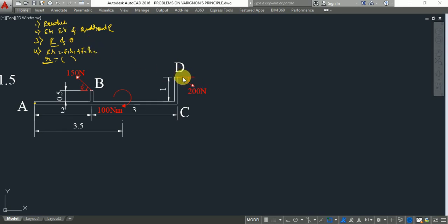See here, the horizontal component is along the given force, so this will be 200 cos 30 degrees. Next, the vertical force will act in the downward direction, and the resolved force is moving away from the given theta, that's why we have sine here.